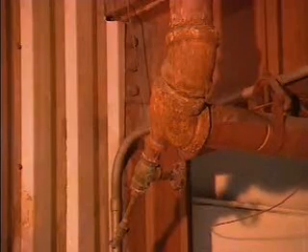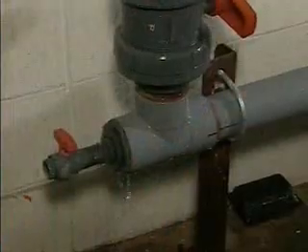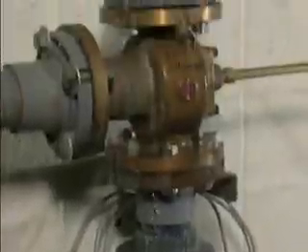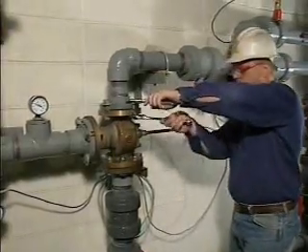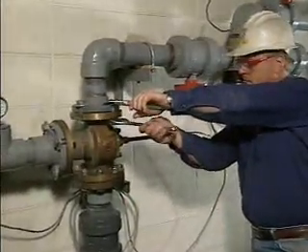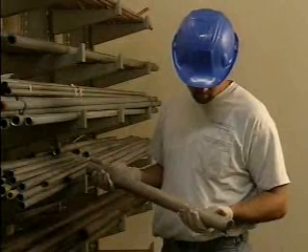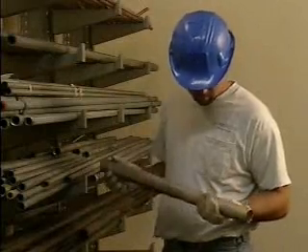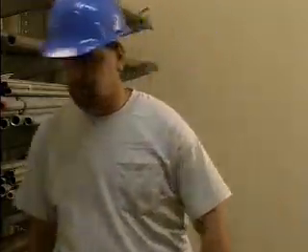Over time, this moisture causes corrosion, which wears the metal away. Any dripping liquid can cause external corrosion as well. To stop continued external corrosion, the source of moisture causing the corrosion must be identified and eliminated. Internal corrosion results when oxygen in the air dissolves into the fluid carried by the pipe. Choosing a pipe material that doesn't interact with the environment, such as stainless steel, will help reduce both types of corrosion.